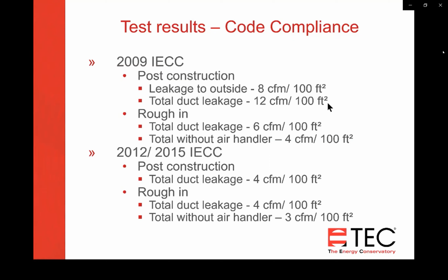The 2012 and 15 code also require an airtight air handler. So that air handler needs to have a stamp on it that says it meets a certain air tightness requirement. You can't put in just any air handler or furnace. It needs to be one that meets an air tightness standard.